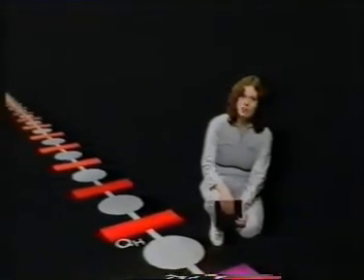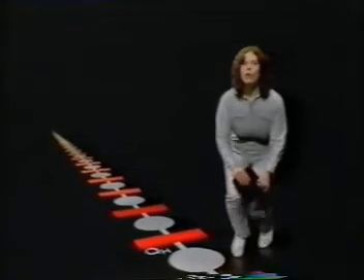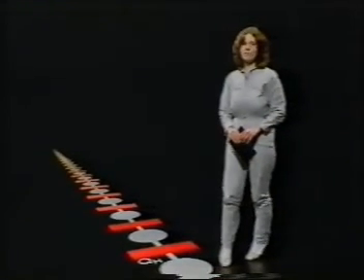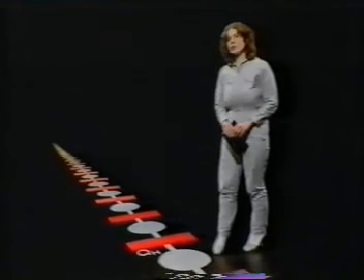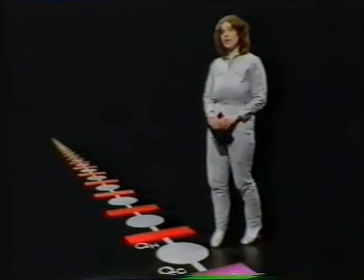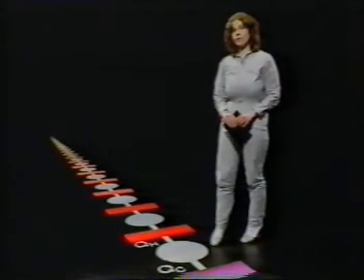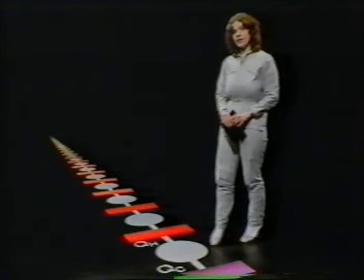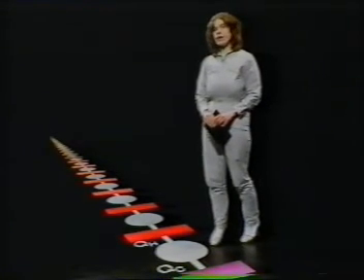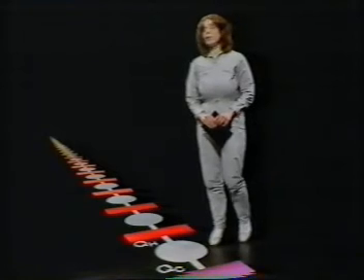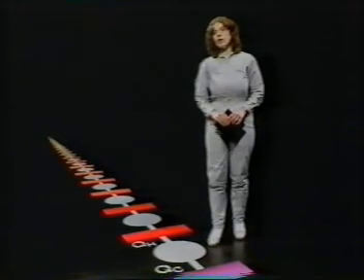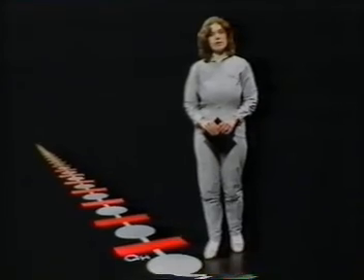Suppose we had an enormous number of Carnot engines, all producing the same work output. That would mean that the difference between the individual QHs and QCs would be the same. And we can use that idea to lead us to an absolute scale of temperature. Now, why would we want that? Well, there are snags with other temperature scales.